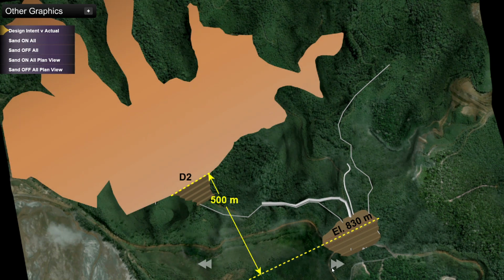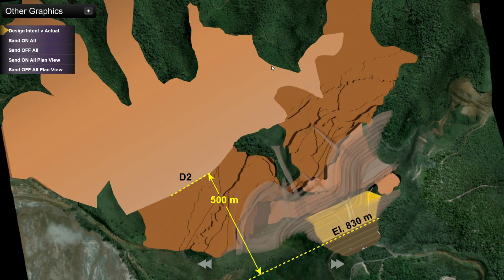The design then shows this mountain valleys and ridges, or gullies and valleys filling up with slime. And then what actually happened was everything should have been back here in the pink area, and all this brown orange stuff was slimes that were in violation of the design down here, too close to the front dam. And of course there's sand stacked on top of that, and all of that was in violation of design and set the stage for this thing to collapse when the earthquake came along.